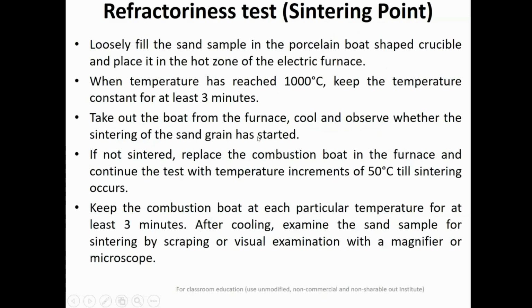So after this, the important property is refractoriness, and many times it is also known as the sintering point test. So sintering point, you all know what sintering is. We have already discussed in powder metallurgy that in sintering all the particles are fused together and bonded together. So you measure that point where the sand particles get bonded or fused together.